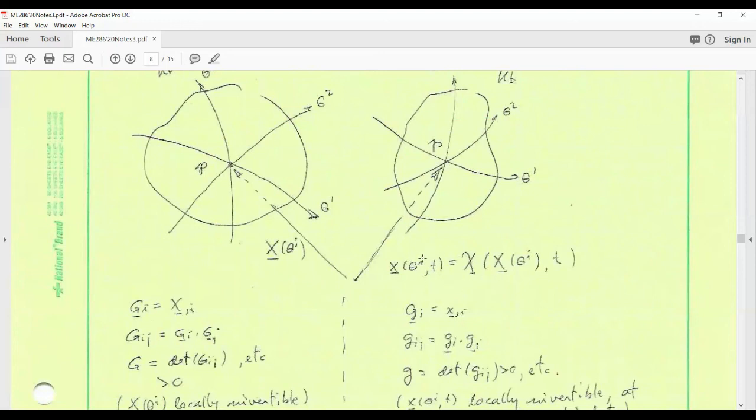Okay? So I obtain that by plugging into my deformation function, reference position given by a fixed parameterization not dependent on time. And then I have an explicit time dependence because the motion itself evolves with time, to give a position function for a given material point identified by its 3 convected coordinates perpetually. That position can change with time. Okay.